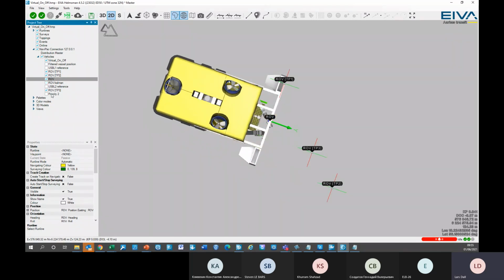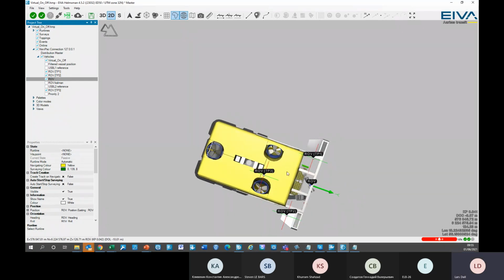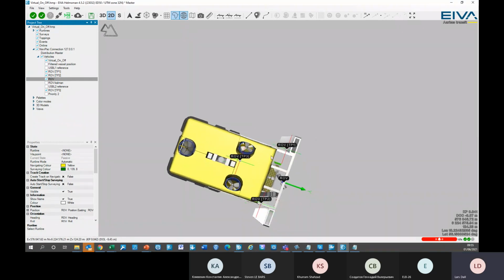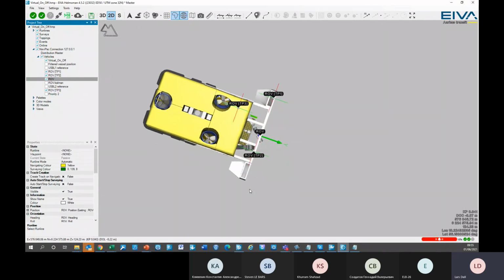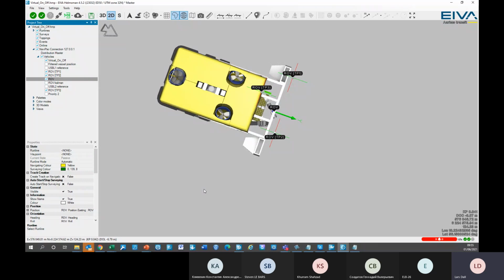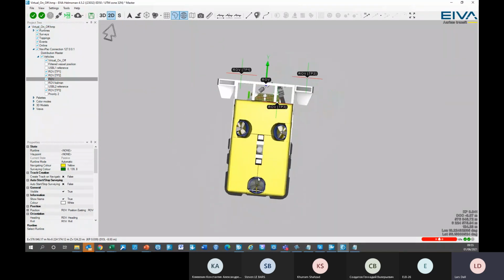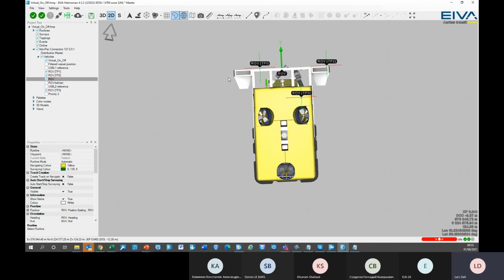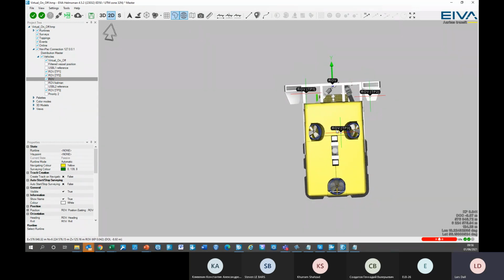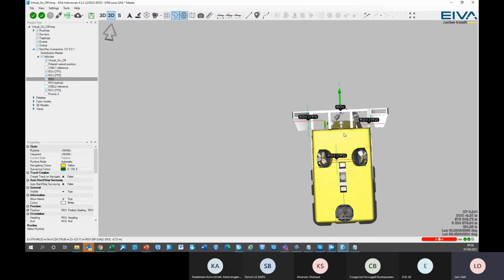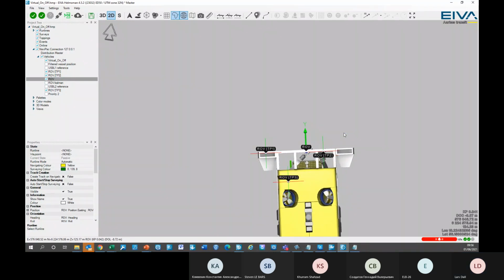Especially if we're not looking at the Kalman. We got the TP1 here, TP3 here, and TP2 here, and that's totally in compliance with what we're expecting, especially if we say that this is our local coordinate system and this is Y0. But they're not going to match 100% because there is noise associated with the data.